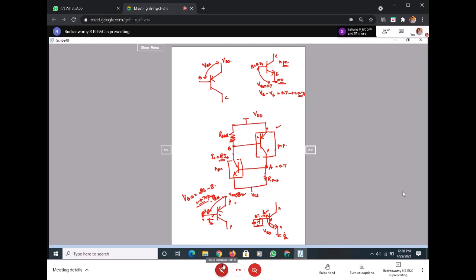And since this is P and this is N, V has to be connected to positive, N is connected to negative or ground, that is okay. But here, what should N be connected to? Negative. P should be connected to positive in order for the forward biasing. And in order to forward bias, again the VBE should be 0.7. And how to get 0.7 VBE?